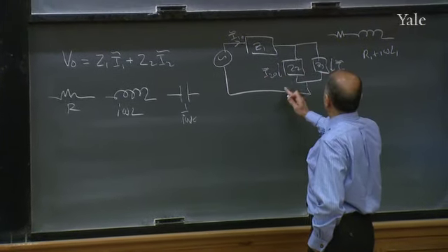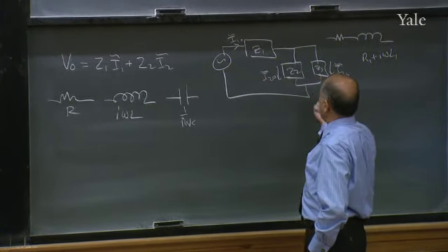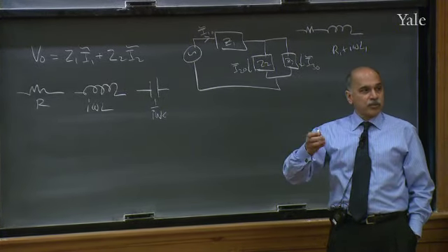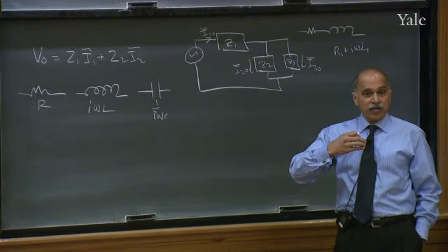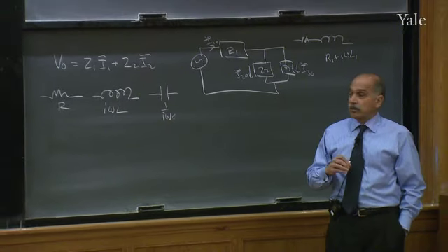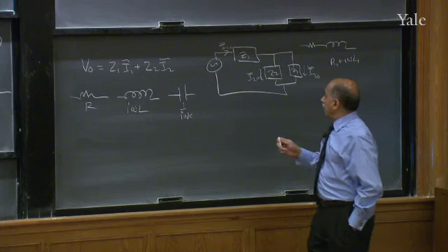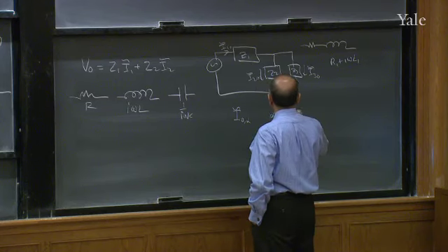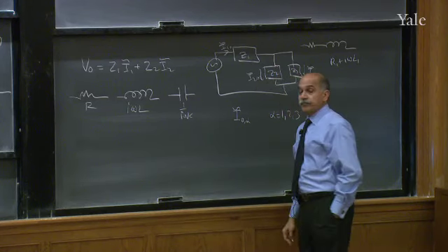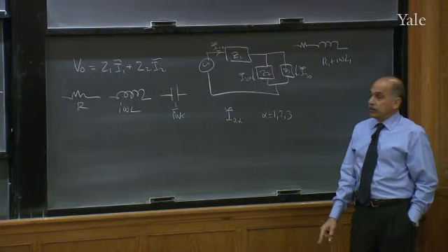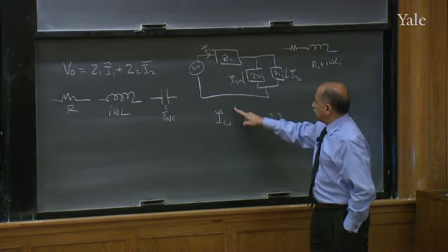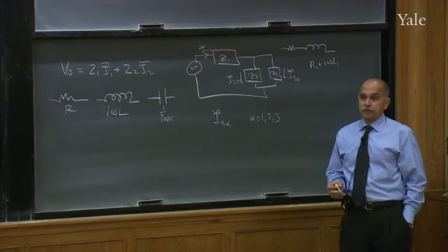Then you can combine impedances in series by adding them, or in parallel by taking the reciprocals, adding them, and then taking the inverse of that. It's all like DC circuits. What will you have at the end? At the end, you would have found every current I twiddle 0, alpha. Alpha is 1, 2, or 3 in this problem, right? You will solve these DC-like equations and find these DC-like currents, but they will be complex.